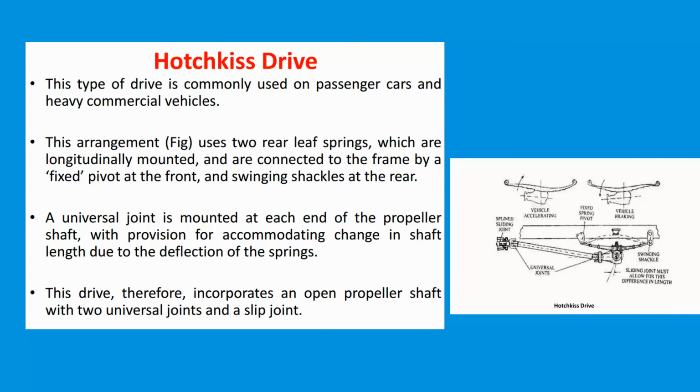In rear wheel drive, the braking applied by the rear brakes is just as important as the power transmission, and the problem is handled in the same manner. Firmly anchoring the axle housing to the leaf spring transfers both directions of torque to the car. This is the Hotchkiss drive.